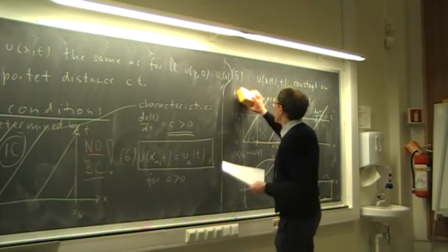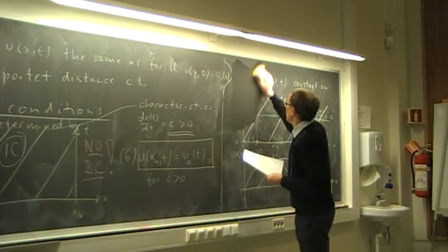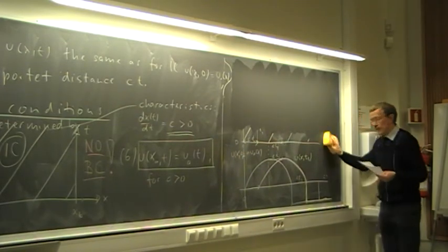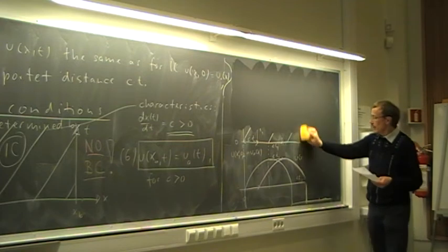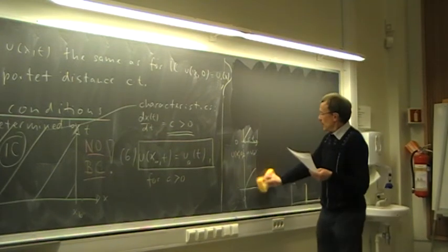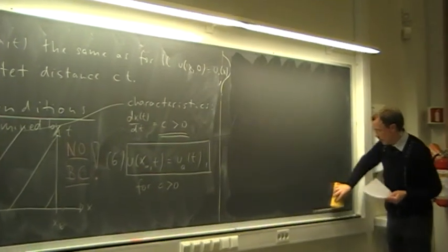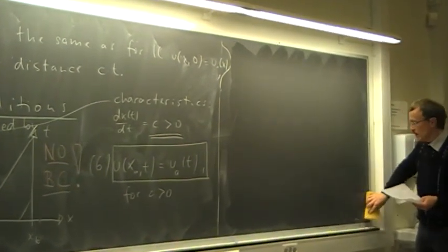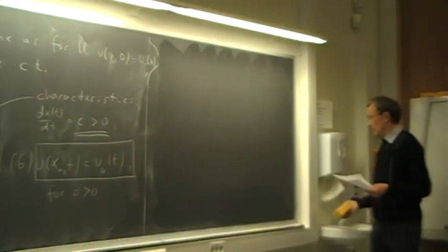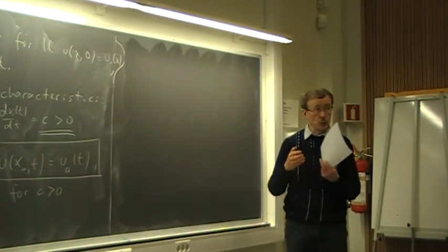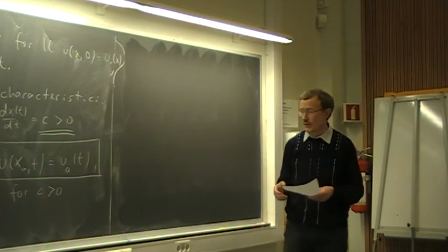This is a point that you will face in every flow simulation. When you are asked to give boundary conditions, then if you have an inflow boundary, you have to give the quantities needed. And at outflow, if it is quantities transported, you don't need to give boundary conditions.